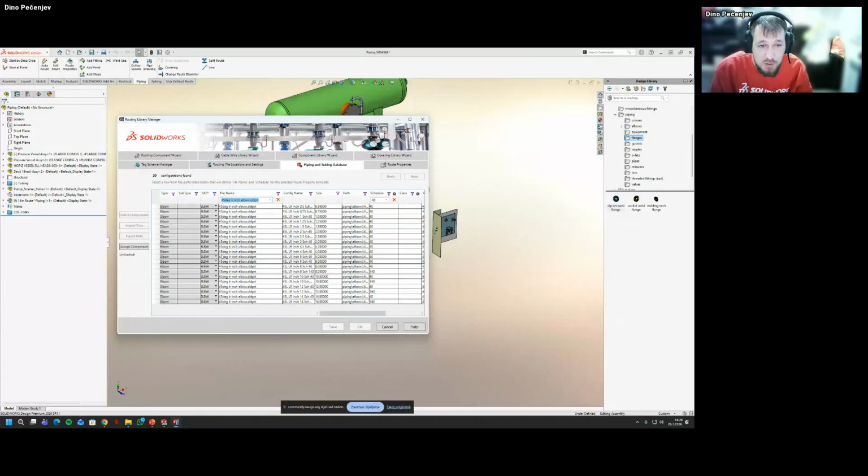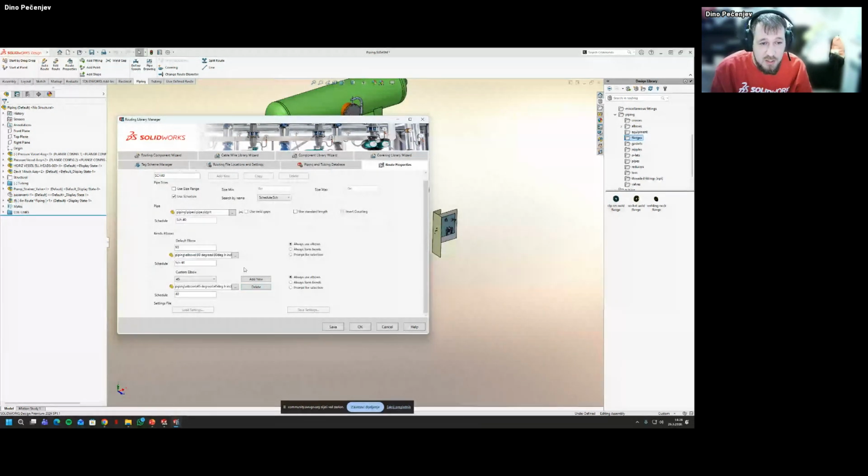We're going to use this one, select the appropriate size and the components. What is important here is that without choosing a specific 45° elbow, we would need to specify it later. But if we use the route specification templates, we can automatically make use of it.